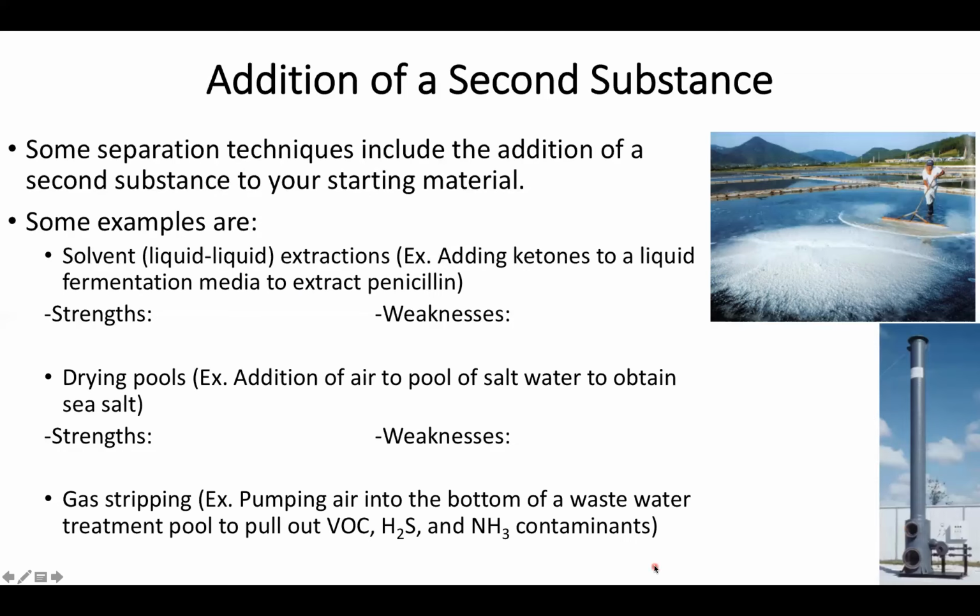So let's say that I'm working with wastewater, and I want to pump out volatile organic carbons, which are often toxic, and ammonia and hydrogen sulfide out of my wastewater treatment plant because these are all environmental contaminants. Well, one of the ways you can do that is literally by pumping air through the system, and all of the contaminants end up in the air that we pumped in.